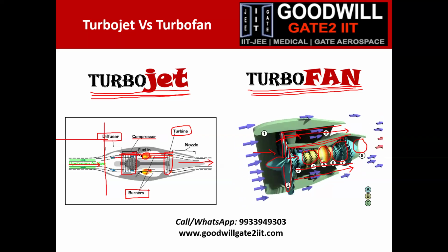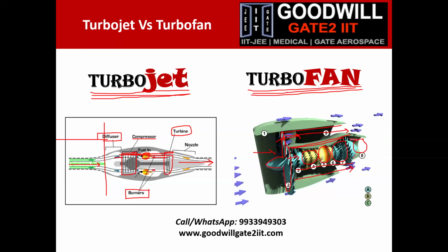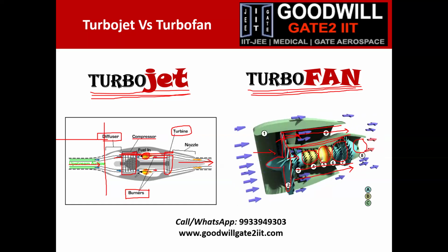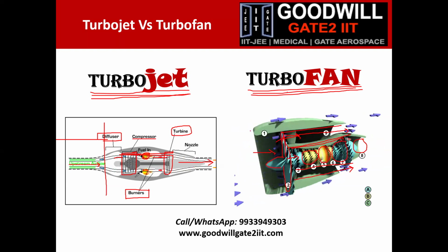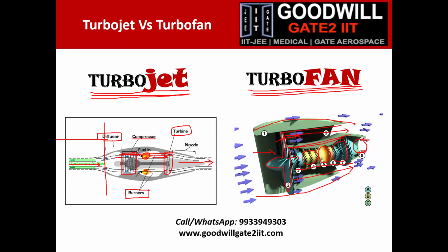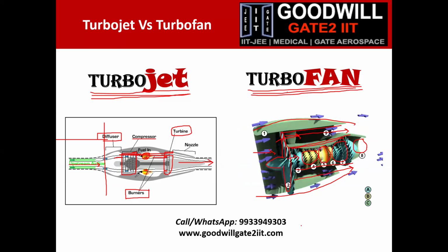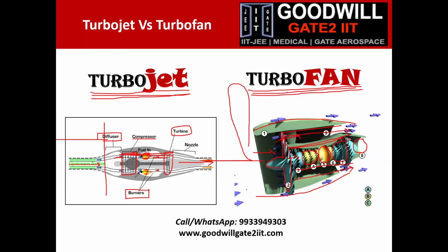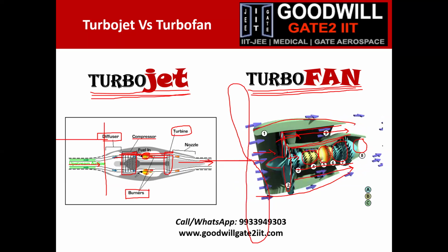As a layman, if you're not particularly into the aerospace domain or propulsion, and you want to look at an engine with the naked eye, the first major difference is that you will not see these big fans in a turbojet engine, but if you see these big fan blades inside the engine cover, then it is a turbofan engine. So just by seeing the aircraft and the engine, you can tell which engine is being used. I'm not going into turboprop, in which you install big propeller blades outside the cowling. Let's not go into that.